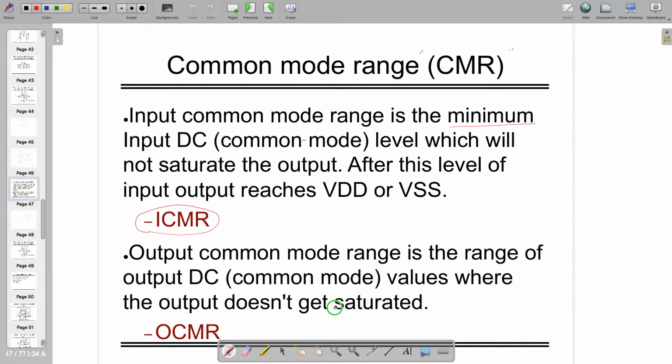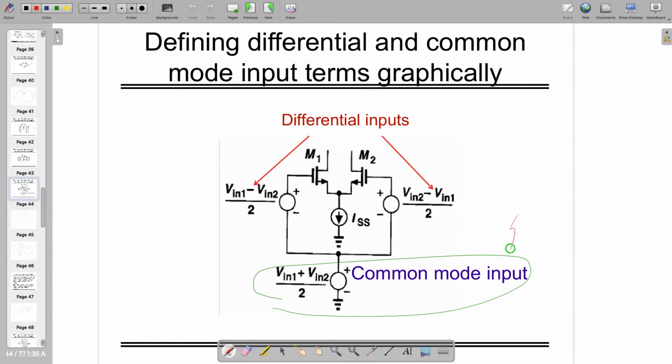These are the things taken from the book, you can read that, and these are standard. The most important part is that you are giving some common mode input from here and observing the output. This value can be found from back calculation, and notably across each transistor, no matter what technology you have, if it is 250 millivolt or greater than 250 millivolt, this works, and we call this one VDS sat.